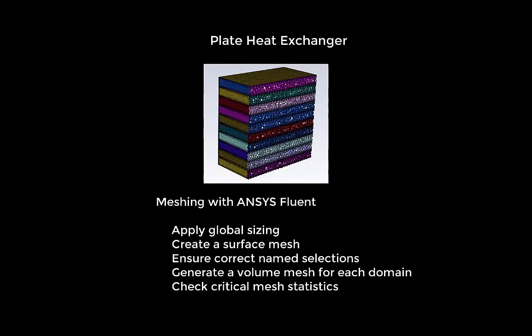In this video, we will create a mesh based on the geometry of a counterflow plate heat exchanger, which we drew previously. We'll create a surface mesh, ensure our name selections were correctly imported, and generate the volume mesh for both the water and oil domains. Finally, we'll observe the generated mesh to ensure inflation layers have been added, and we'll review critical mesh statistics.